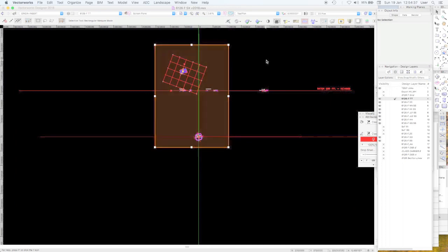This gives a consistency. You can, of course, just rotate it and stick the drawing wherever you like in the page. Please at least put the floor levels in a line horizontally so that you're in control of the vertical coordination of section and elevation. Strictly by the book method is to rotate this.